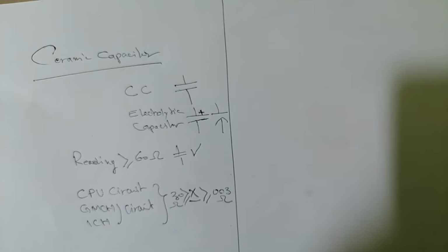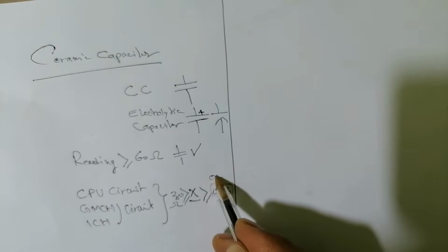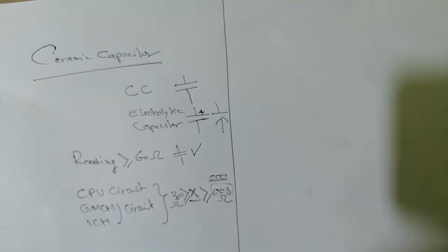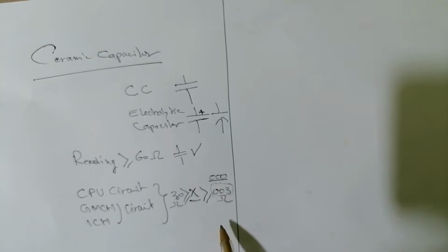If it's the CPU, if you can remove it and check, it will be better. But if the chipset is integrated, anyway, a low value doesn't mean a short circuit unless you find 0.000, three zeros. If you find three zeros, it means automatically you have a short circuit.